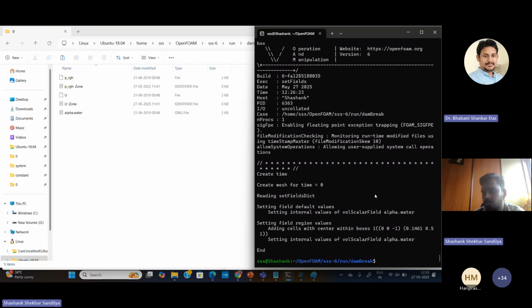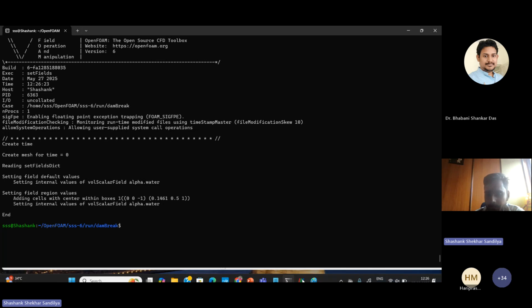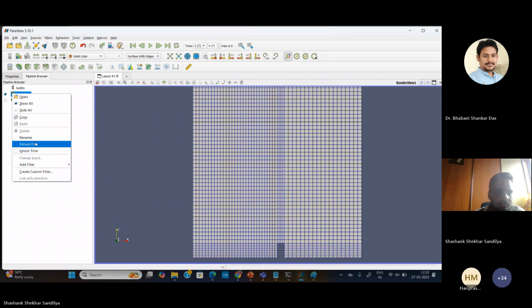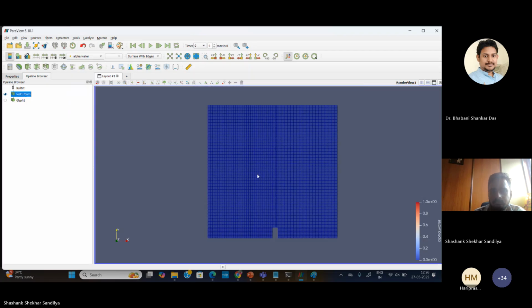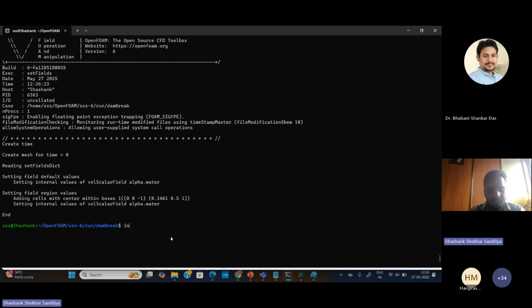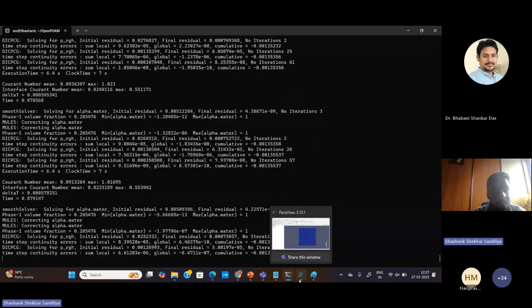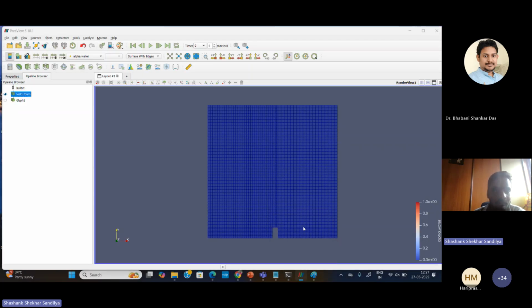So these are the old block mesh. So now it works. So now the height is up to 0.5. We will see that also here. Previously we saw that it is up to 0.29. Right? So actually it will be there if I run the software. It is not showing at the 0 time, that's why it is taking time. Actually, we have increased the number of meshes, so it takes a longer time. We have increased the meshes in the X direction from 23 to 30. So that's why this time it takes longer.